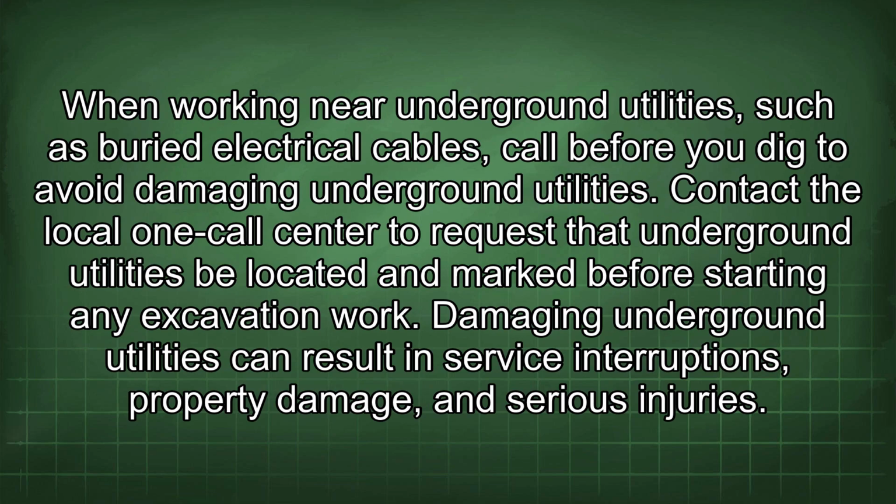When working near underground utilities, such as buried electrical cables, call before you dig to avoid damaging underground utilities. Contact a local one-call center to request that underground utilities be located and marked before starting any excavation work. Damaging underground utilities can result in service interruptions, property damage, and serious injuries.